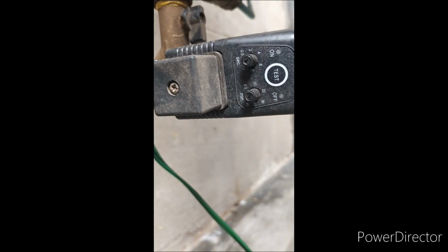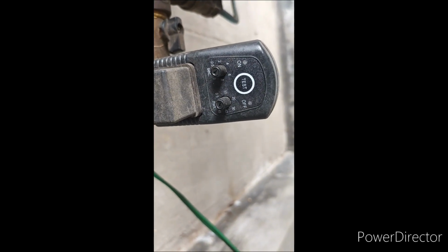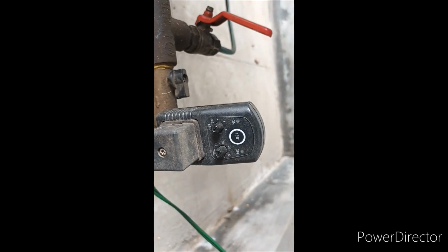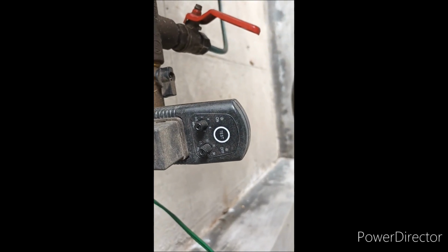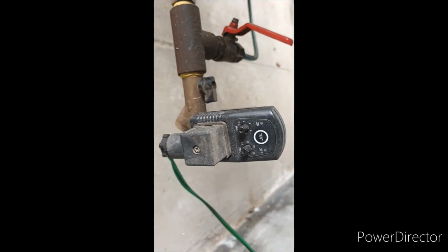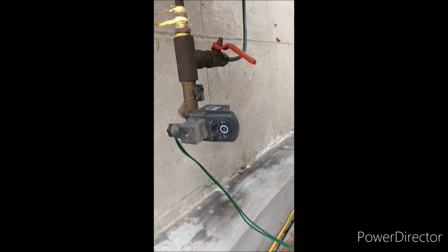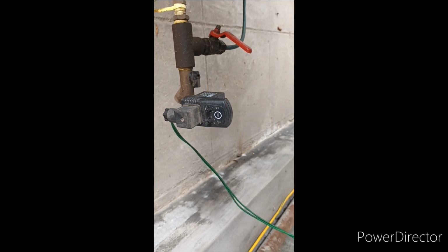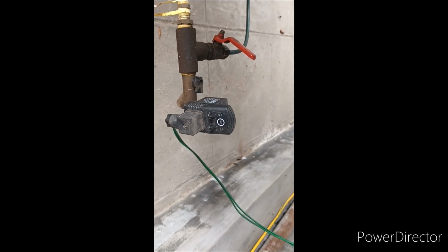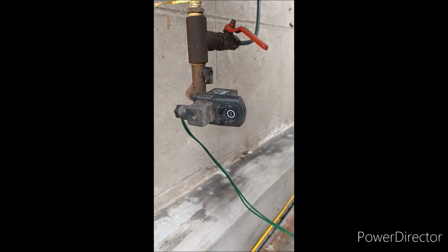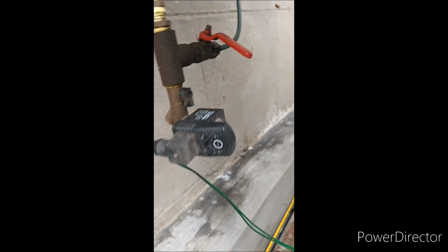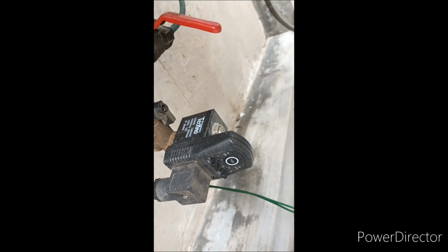Manual removal of moisture can damage your air compressor. For example, most air compressor manufacturers use a manual valve to drain the moisture from the oil tank. In the manual process, the water is drained by humans every day, so there is human interference. The auto drain valve is a single phase solenoid coil, mounted into the air line, with an on and off electrical supply for this. The drawback of manual draining is that it depends on the human.